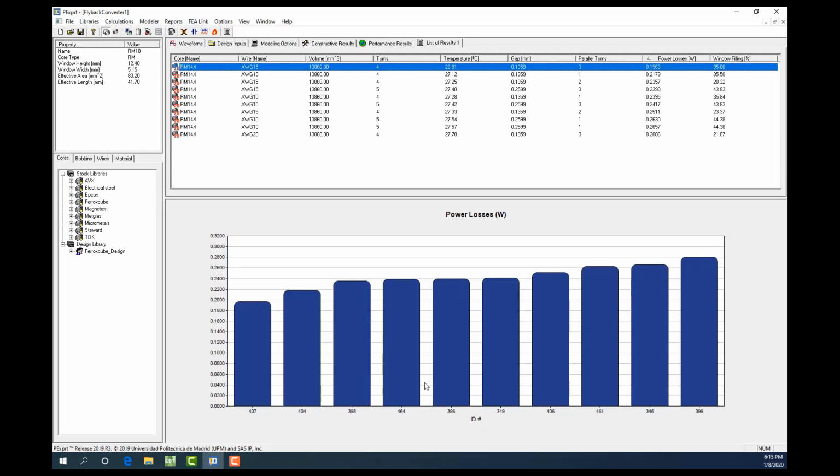In the previous PExpert video, I showed you how to quickly create the analytical solution for transformers using PExpert. In this video, I'm going to show you how to create the PEMAC model based on the PExpert model and extract the resistance, inductance, and capacitance using FEA solver, which is also the Maxwell solver.